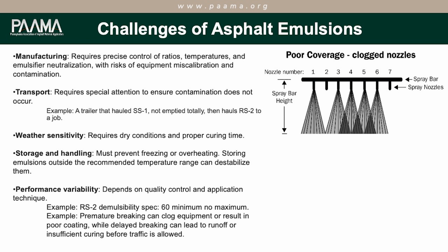Storage and handling, you don't want to freeze it, you don't want to overheat it. Storing emulsions outside the recommended temperature range can destabilize them and cause them to flip. Basically the asphalt and the water. You'll have asphalt at the bottom of the tank and water on top. Nobody wants to deal with that.